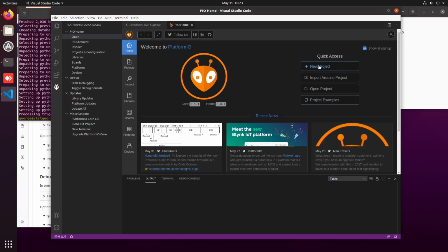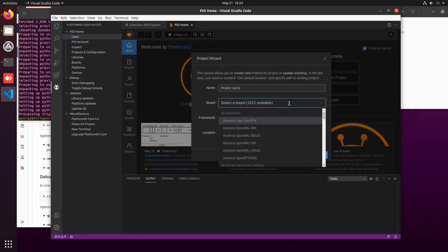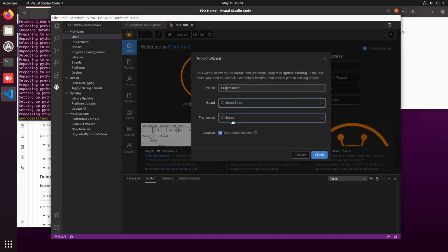First thing we are going to do is that we are going to create a new project, so you see how it works. And our project is an AVR assembly code project that we want to run in an Arduino Uno board. So we go directly here and we look for Uno, okay, Arduino Uno. It will select for us then the framework and the tool chain that we have to use. We give it a name. We are going to call it example